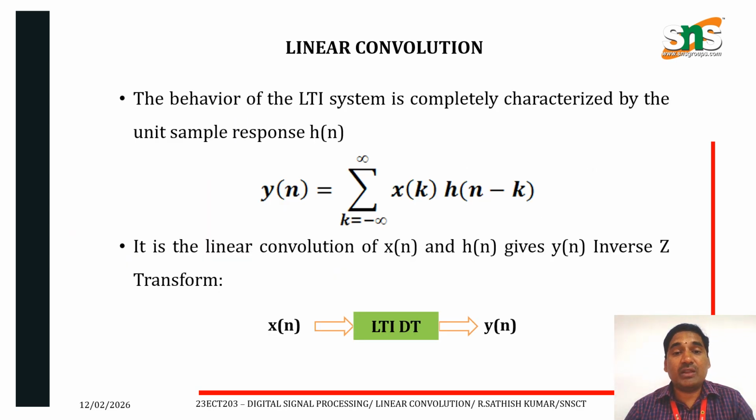Next one, the behavior of the LTI system is completely characterized by the unit sample response h of n. y of n is equal to summation k equals minus infinity to plus infinity x of k into h of n minus k. It is the linear convolution of x of n and h of n that gives output y of n.